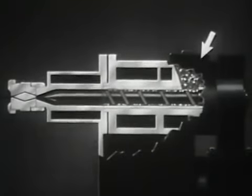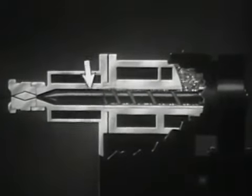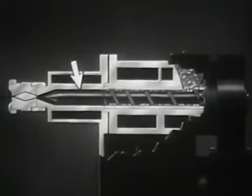Here the material is placed in a hopper. Then a continuous screw forces it into the heating chamber. Heat and pressure soften the material, and it is forced out through the die opening in hot plastic form.